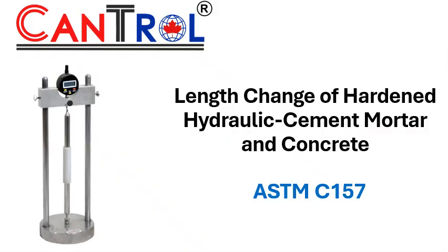The procedure involves molding prismatic specimens, curing them under controlled conditions, and measuring their length at regular intervals. The results are expressed as a percentage change from an initial measurement. This test is crucial for evaluating the potential for cracking and dimensional instability of concrete and mortar mixtures.